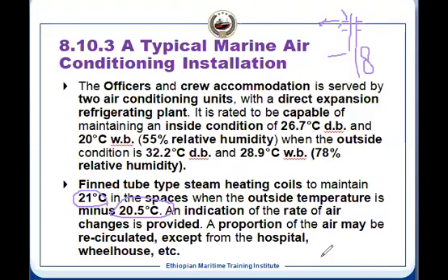So another thing, when it is passing through this, there is another consideration we need to make, that is the rate of air change provided. It means when you are supplying, there is a mass flow rate that has to be maintained. It means when it is passing through that, you need to calculate how much time it will take to pass through. Within that time, the heat transfer has to take place.